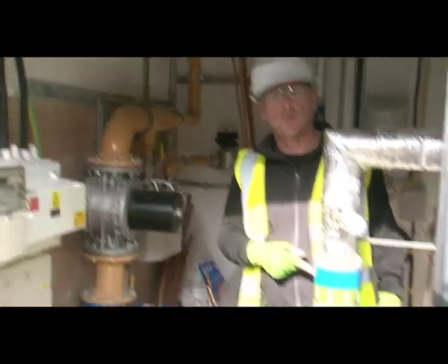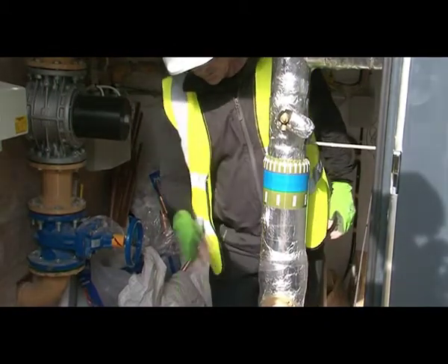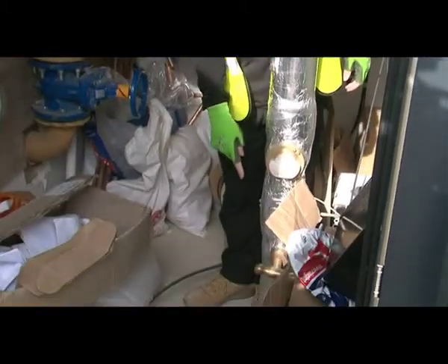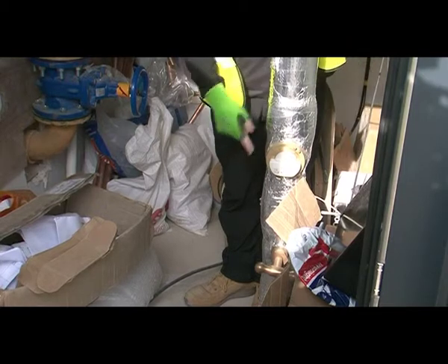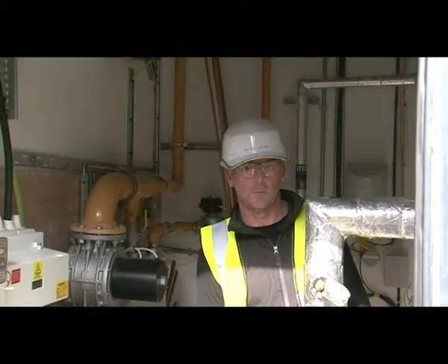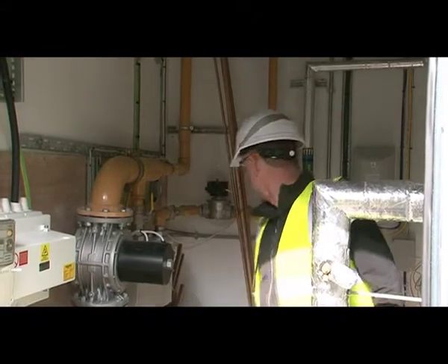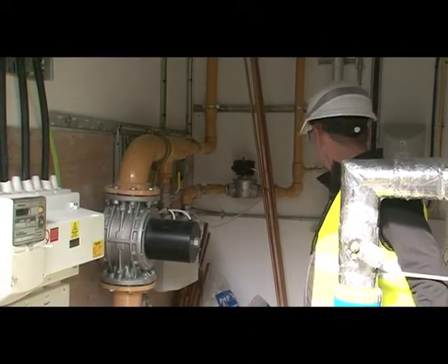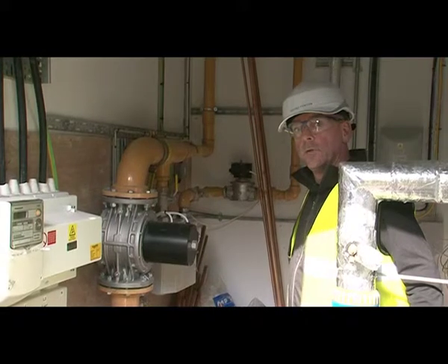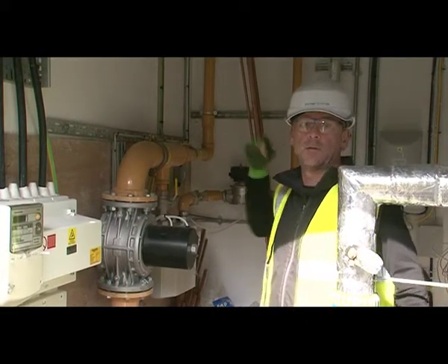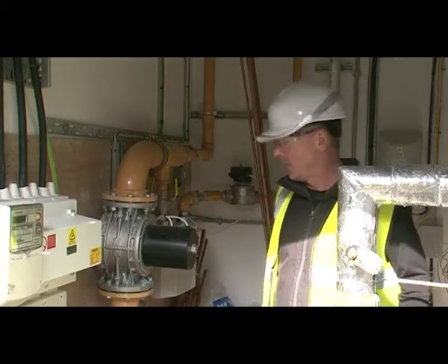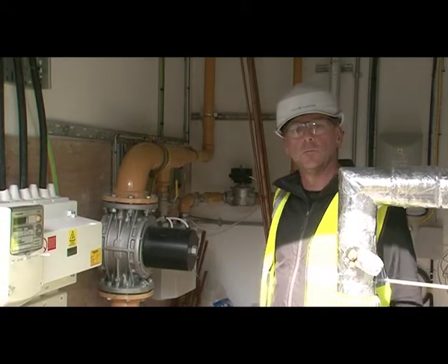Here is where the mains cold water comes in, and its main isolation down the bottom. It also has isolation valves further up, which are less accessible. This is the one. And you also have your Cat 5 booster supply coming in there as well at the back, but that can be isolated from the booster set in the plant room. This is the incoming services room.